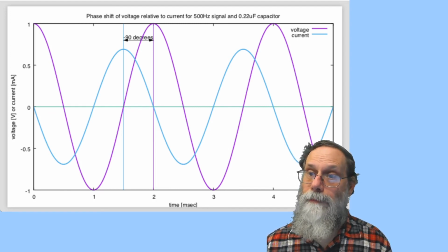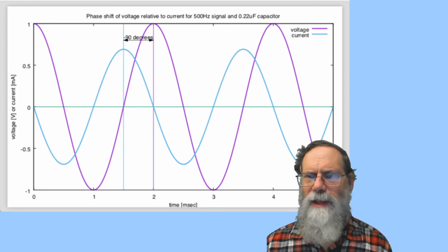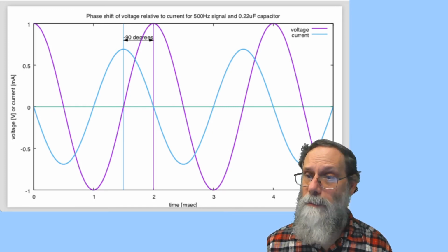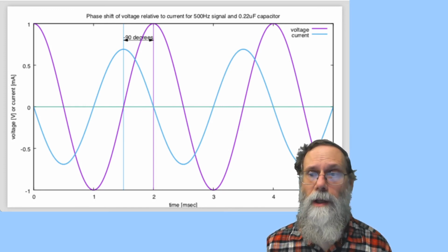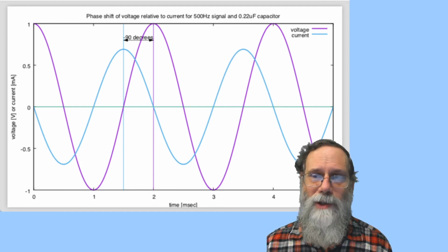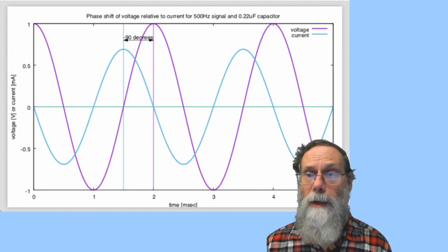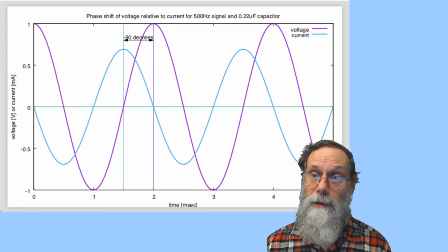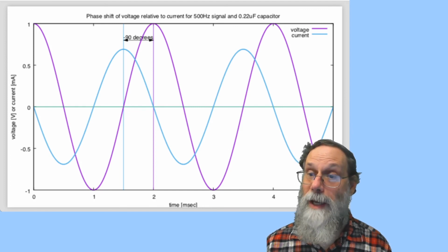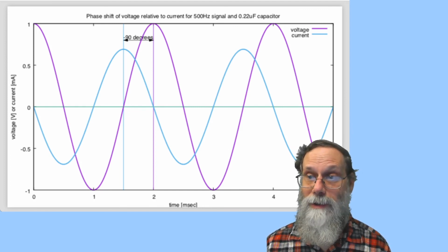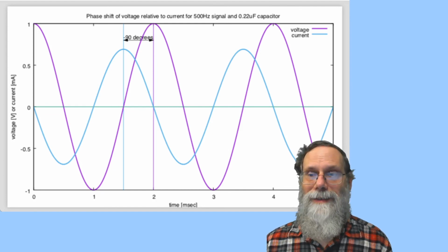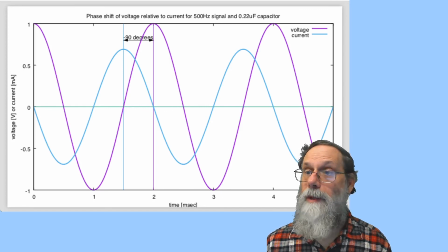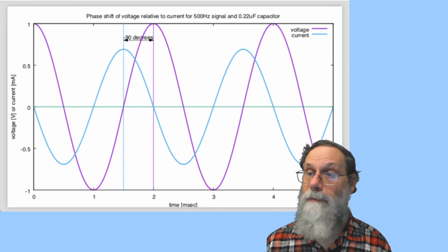Okay, we'll look more at phase shift a little bit in this class, but for the most part, we're going to be interested in the magnitude of impedance and not so much in the phase. So if the phase shift is bothering you a little bit at the moment, don't worry about it too much, but do try and understand what happens to the magnitude of the impedance. And do always keep all your calculations in the full complex numbers, because when you add and subtract things, the phase matters then. Okay, that's probably enough for now on the impedance of capacitors.